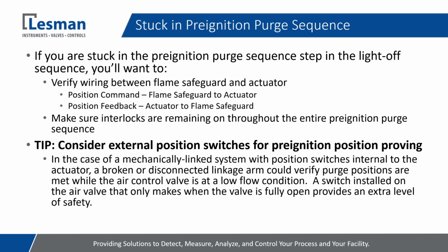I also just wanted to add here a tip for those of you who are into doing system design or selecting components. It just adds a little bit of an additional safety factor, in my opinion, on your systems. Instead of using position switches that are internal to the actuator, you may want to consider using external position switches that are physically connected to the valves.